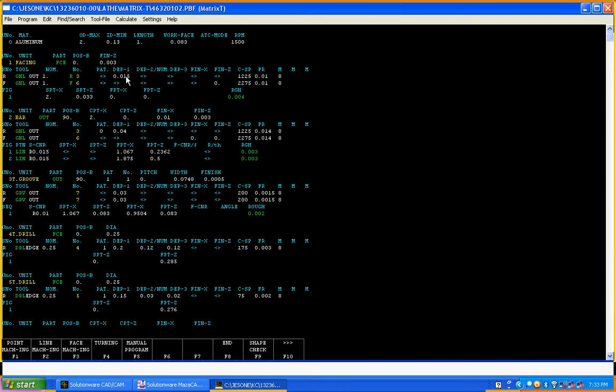All right. So as you can see, it's going to face, and it's going to take 15 thousandths. And here, actually, we just need to change this, the SFM, right? So as you can see here on the top, it's going to be aluminum. The stock diameter is 2 inches. And it's saying here that the minimum diameter, or the ID diameter where there is a hole, is 130. Actually, you know, I just say 0 all the time. I say 0 because it's bar stock, and this program originally was done by someone else.